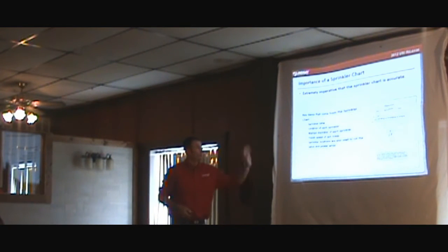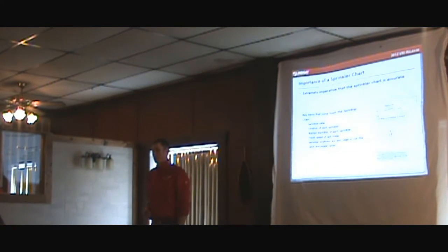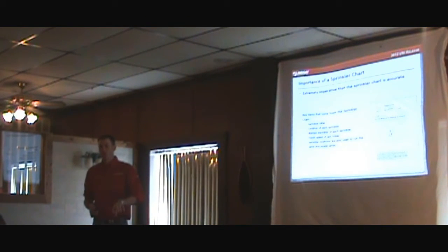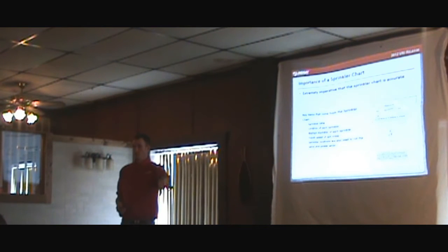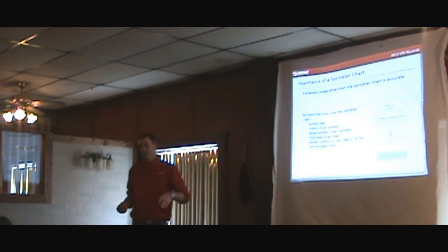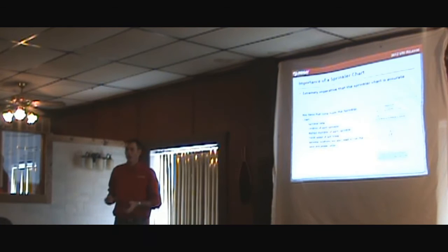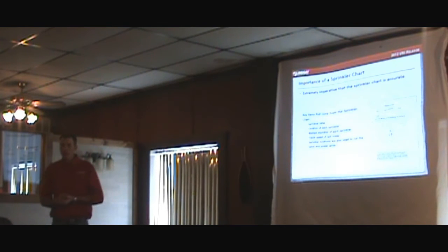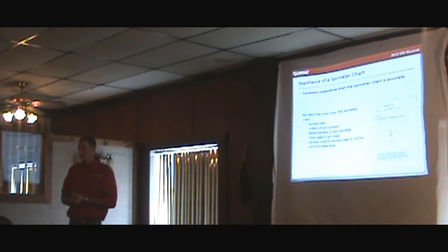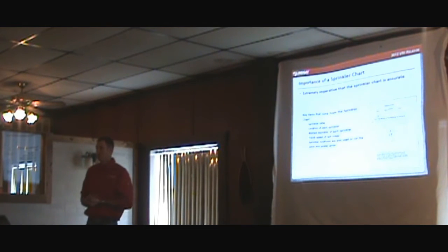Sorry about that. The sprinkler chart is obviously very important, because everything that is in the sprinkler chart we dump into the VRI system. We recommend that if you've got a 7 or 8-year-old sprinkler package and you're not going to re-nozzle it, the dealer maybe walks the machine quick and makes sure the chart reads what's out here. Just take a few minutes to validate. If it's a newer machine you've never touched and you're pretty confident of it, make your own decisions on that. If your sprinkler package is borderline wearing out, that's a judgment call.